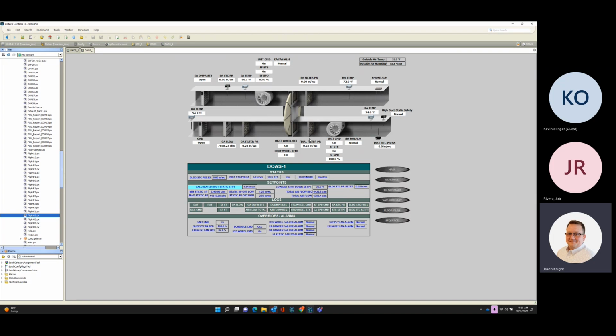So you have three types of fan coils. You have fan coils that have ECM motors. You have fan coils that have VFDs. And then you have 3-speed fan coils, meaning there's no modulation other than low, medium, high. Okay. Now, depending on the mode of the fan coil, if the fan coil is calling for cooling, we were given a cooling fan speed we had to maintain.